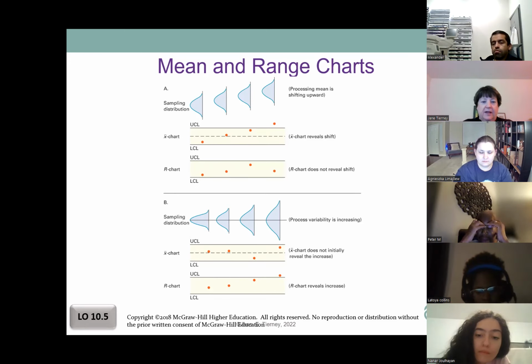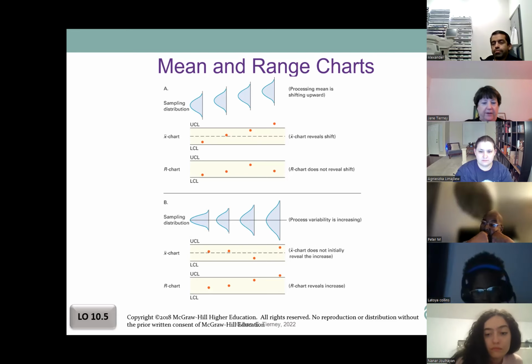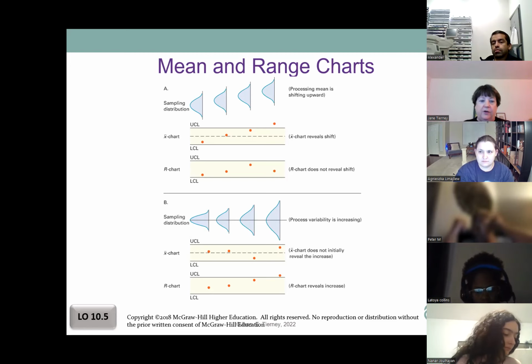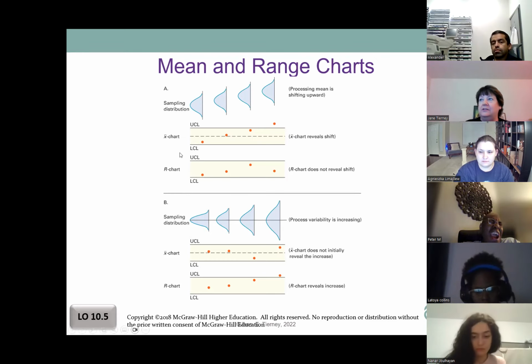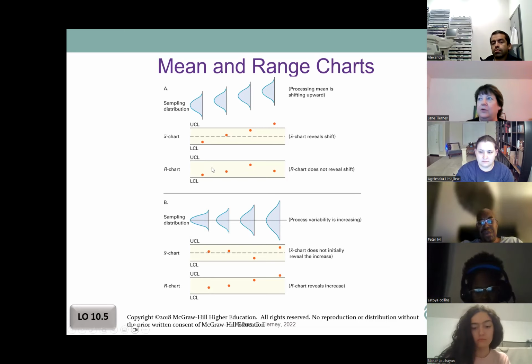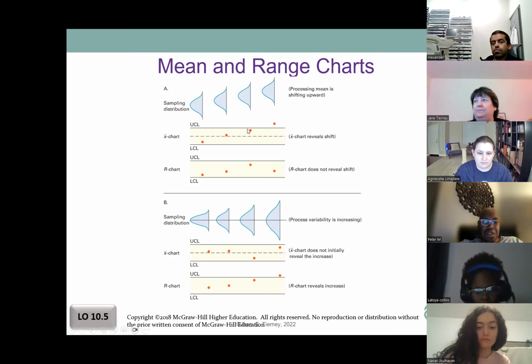So what happens is, if you're measuring that hole diameter, your holes are going to get smaller and smaller, right? It's not going to be a 1/2 inch. It's going to be less than a 1/2 inch because your drill bit wore down a bit. And it can't drill a hole that's the right size. So you're going to track that over time, and again, your average is going to get smaller and smaller. In this case it looks like it's getting larger, but that's an example of what this would be: oh, your drill bit's wearing out. So now you need to go fix the drill bit, right?